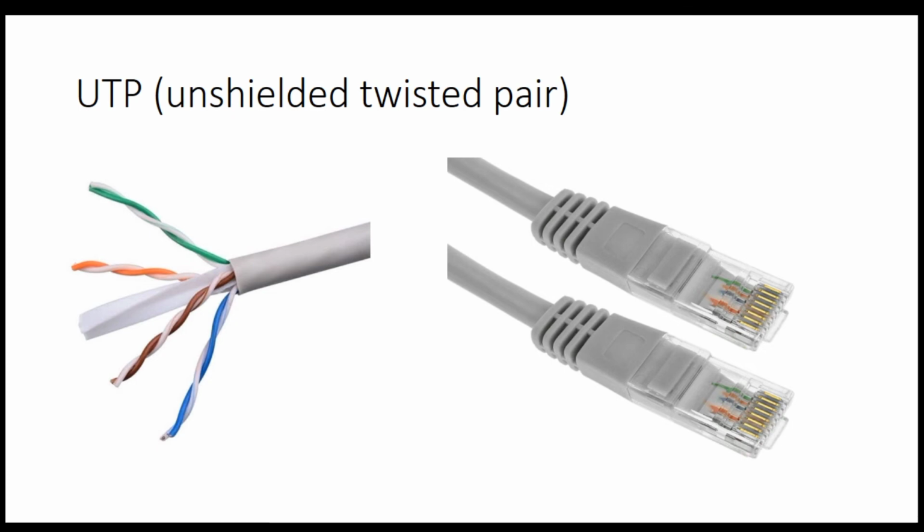Cat6, Cat6A and Cat6E standard UTP cables are used in all data center cabling works due to their robustness, reliability and efficiency. Standard patch cables have many fixed standard lengths like 1 meter, 3 meter, 5 meter, 10 meter, 20 meter. A UTP roll is 305 meters long and is used to extend cables with lengths higher than the standard cables and is terminated by RJ45 or directly in the patch panel.